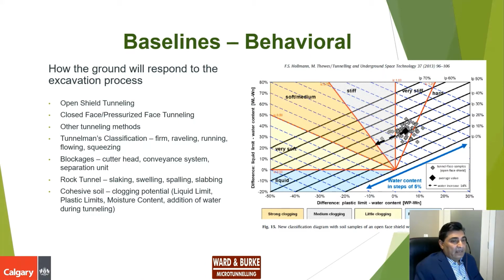Behavioral baselines is basically the behavior of the ground during tunneling. For example, if we are in saturated gravel and we use an open face microtunneling boring machine, then the saturated gravel will flow into it. So this is a behavior.